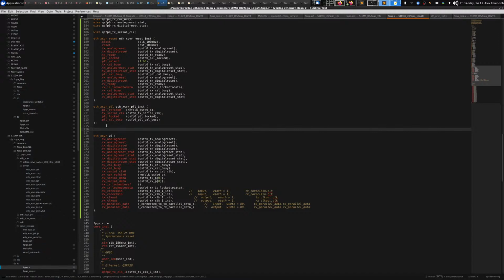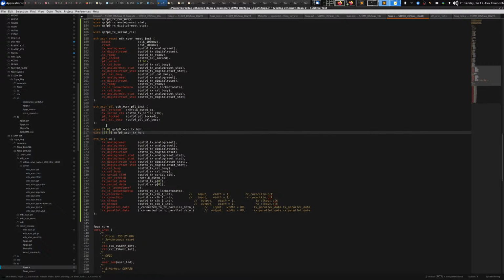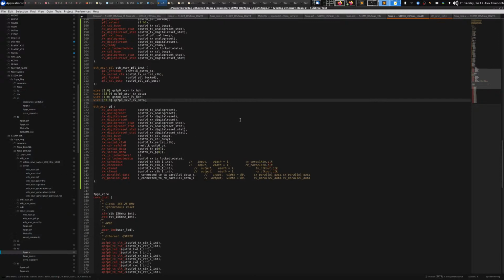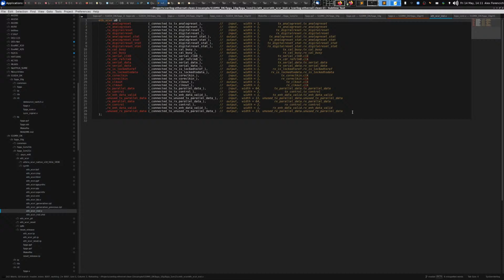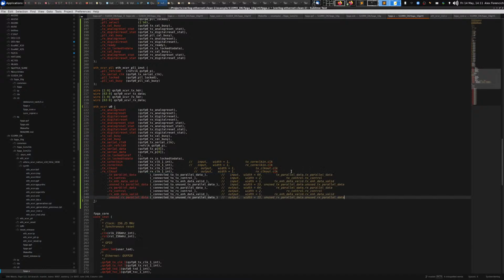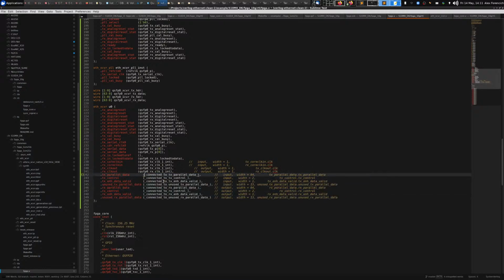So this is going to be 64 bits of data plus a 2-bit header. Okay, so this is going to be the TX header, and this is going to be 2 bits. And then 64 bits data. All right, so there's the TX, and then we have the RX. Okay, this did update. Excellent. Yeah, all right, so that just replaces these last 2 lines here, like so.